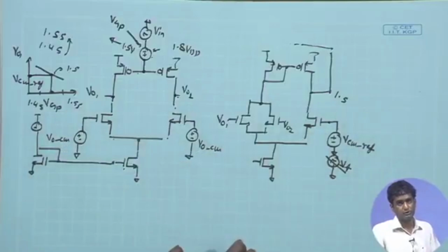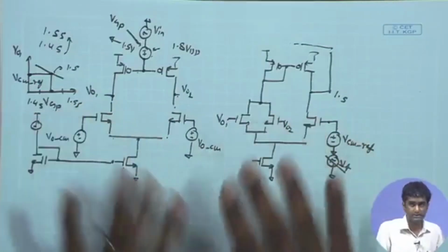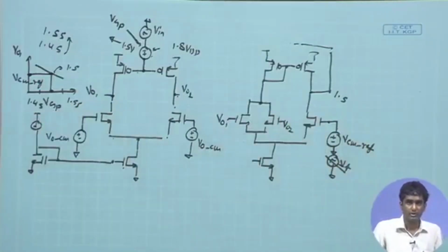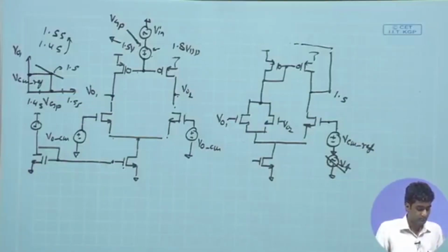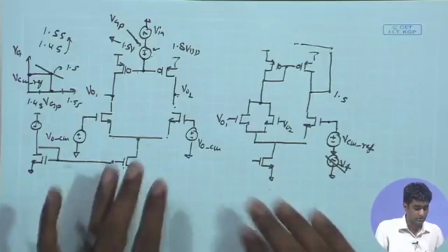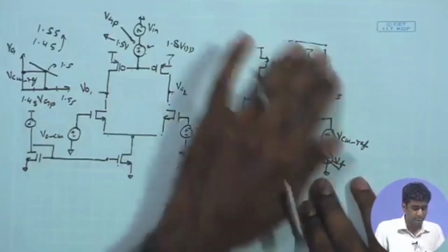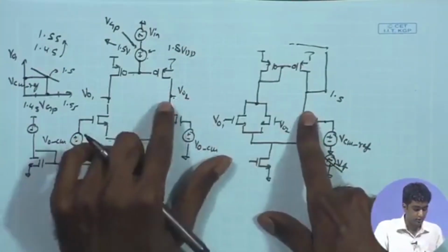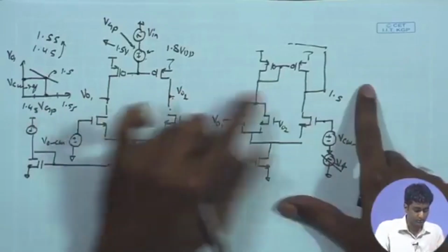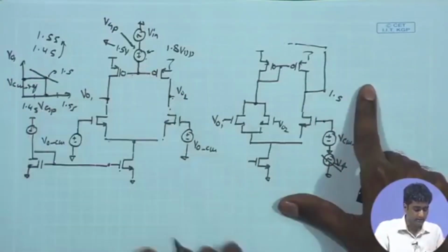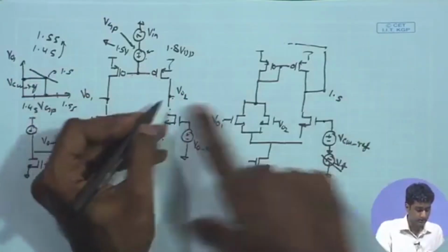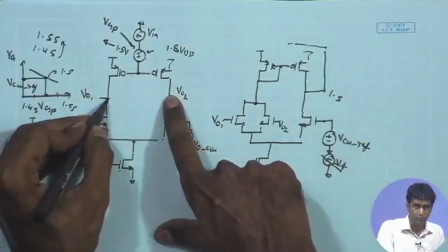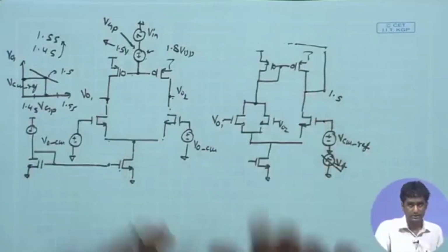So, here I have just tried to complete the analysis from the simulation point of view, how you will be doing the analysis in real simulation to obtain the overall phase margin. And likewise, if you are looking at compensation, once again you are either going to look into the capacitances placed between the output over here and this point, or the capacitance placed between the output node over here and the output here.